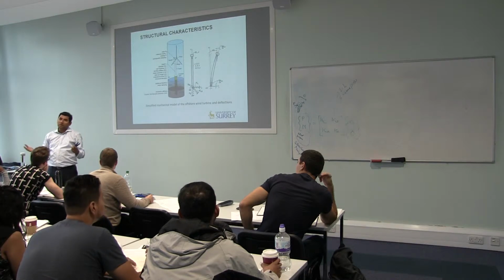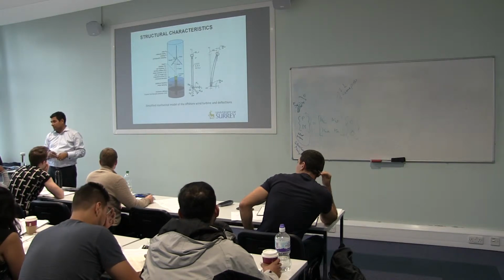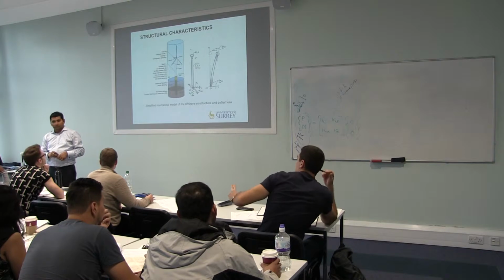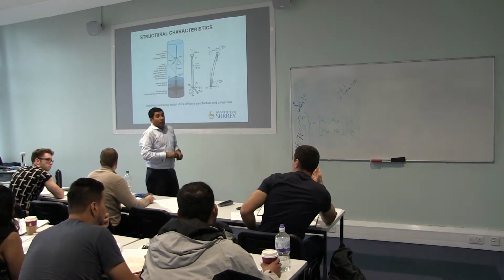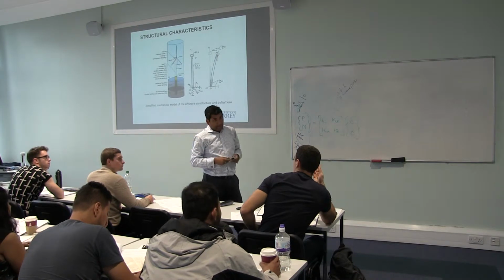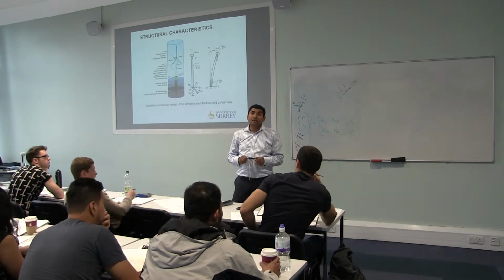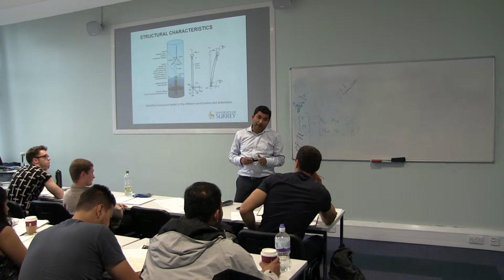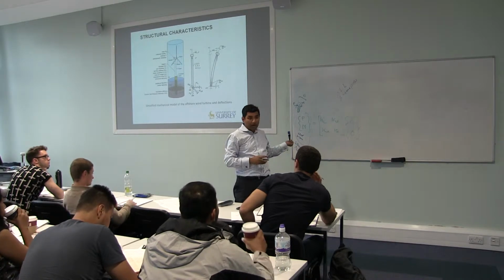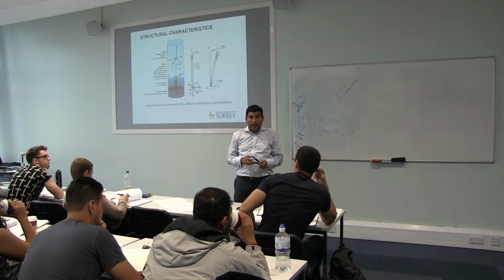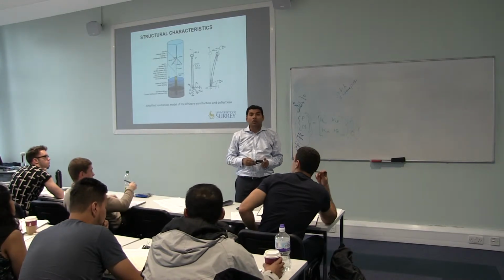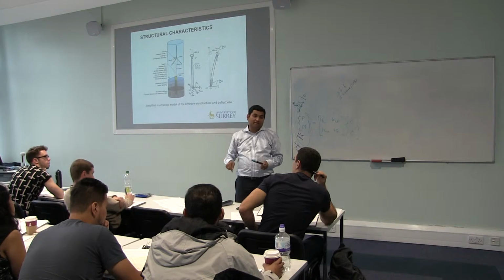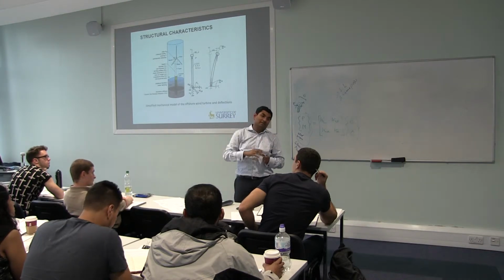You make it bigger so that you comply with the requirement. But you said there's no kind of requirements, who's producing the requirements then? There is. The turbine manufacturer does a code of practice, DNV code of practice for monopile design. And the turbine manufacturer will tell you, you've got to satisfy these things. You can't have more than this tilt.